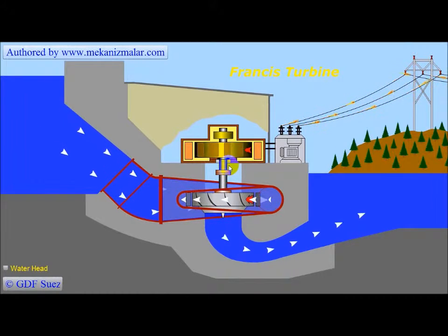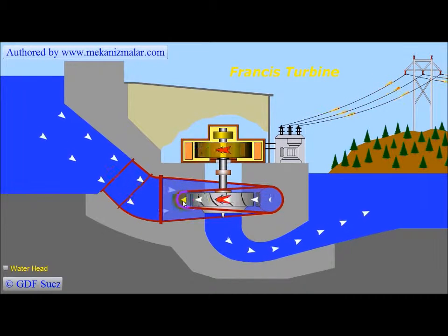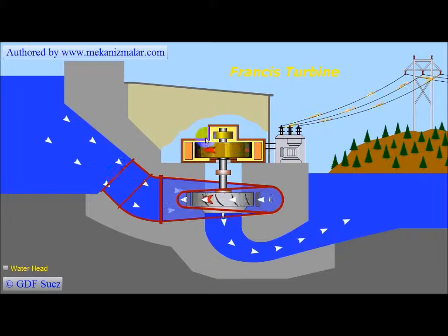The turbine shaft of the Francis turbines is almost always mounted vertically. This makes discharge of the water much easier due to swirling effect of the water in the inlet scroll, and the effect of gravity. The rotation motion of the runner is transferred to an electric generator shown here. The generated electricity is converted to high voltage current and transferred to the grid to be consumed.